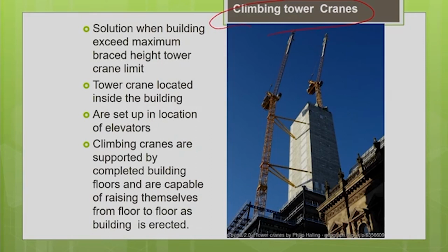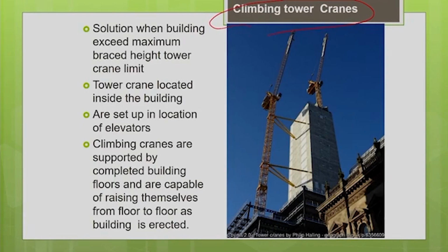We usually provide it in the opening of the lift or the elevator. So, in that location you can place this tower crane. Initially, to start with, it will take its support or base from the foundation of the structure, the actual foundation of the building.